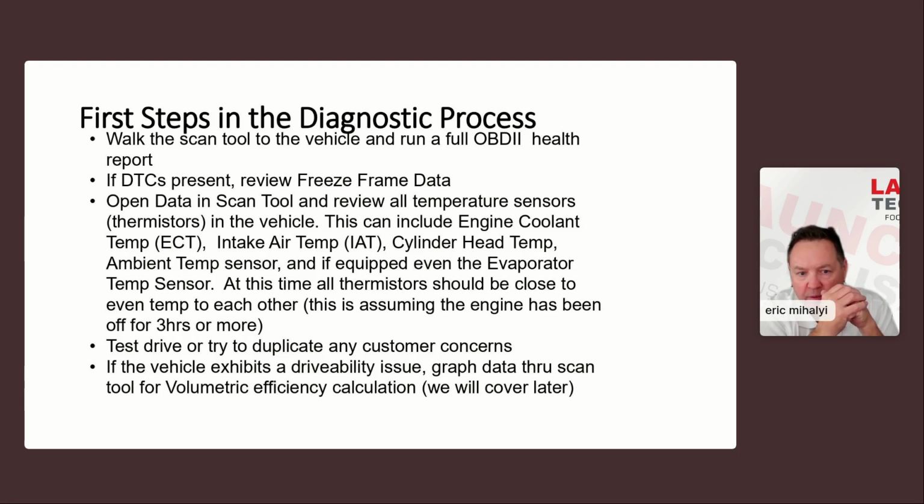Cylinder head temperature, going back to what an engine coolant temperature sensor would be, right? Ambient and evaporator temperature sensors. I've seen situations where people are chasing inoperative HVAC or various other functions with the car, and the problem is that the ambient air temperature sensor is shorted out, and they can either go real low or real high, like a number that couldn't possibly be, right? I've looked at an ambient air temperature sensor using this procedure and seen it's at minus 88 degrees.